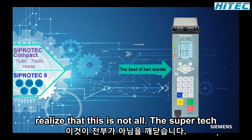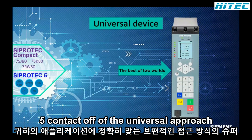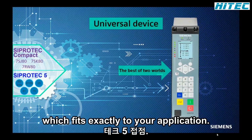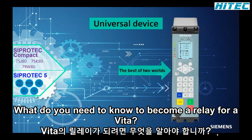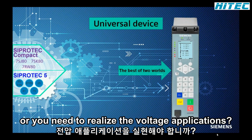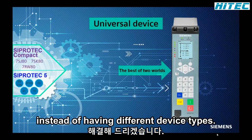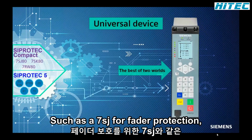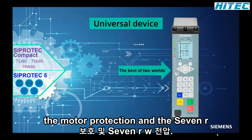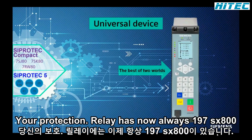But this is not all. The Supertech 5 compact offers a universal approach which fits exactly to your application. Whether you need an overcurrent relay for a feeder, you want to protect the motor, or you need a relay for voltage applications, we've got you covered. Instead of having different device types, such as the 7SJ for feeder protection, the 7SK for motor protection, and the 7RW for voltage and frequency applications, your protection relay has now always one name, the 7SX800.